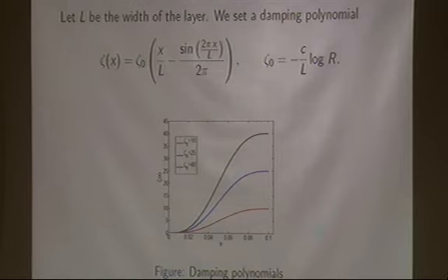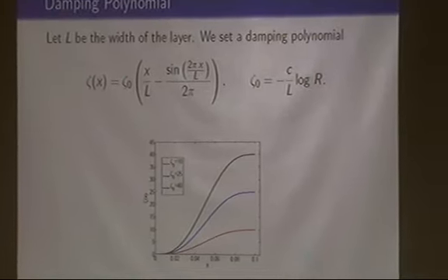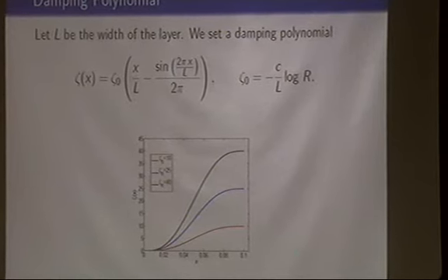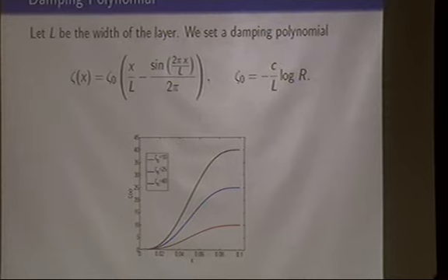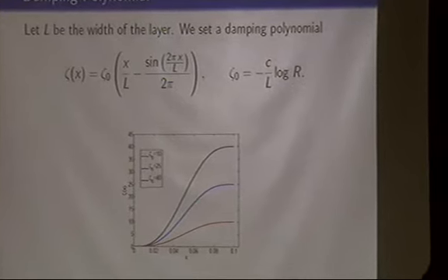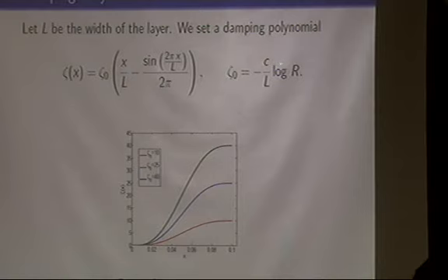You can control theta 0 with the reflection coefficient. So a priori you can say, for example, I want just a reflection coefficient of 10 to the power minus 3, then you can put just this. And regarding the question of Professor Lim, the size of the layer you can put also, and it also depends on the wave speed. So you can put these parameters here, and then you can also control the layer of the PML.